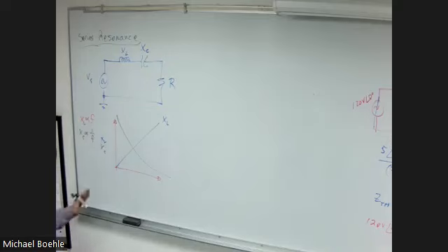At low frequencies, the circuit acts capacitive, because the capacitive reactance is a lot bigger and cancels out the inductive reactance. But at high frequency, the inductive reactance dominates, cancels out the capacitive reactance, and the circuit acts inductive.